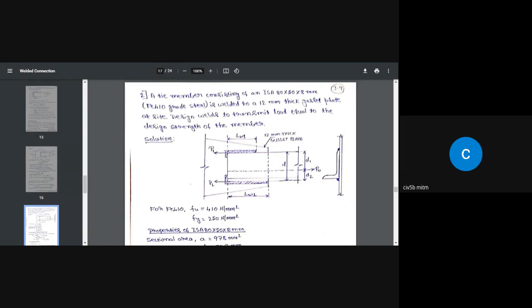If you go to page 22, again, that covers equal angle sections. So let us go to page number 24, rolled steel unequal angles. This is where we have to look. Unequal angles means two different leg sizes.